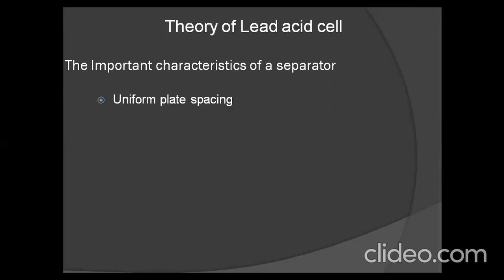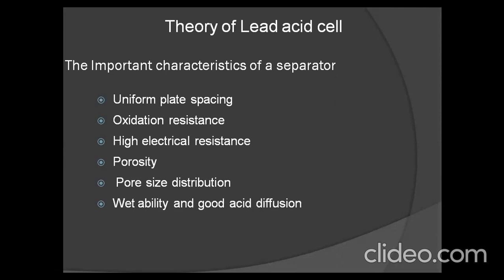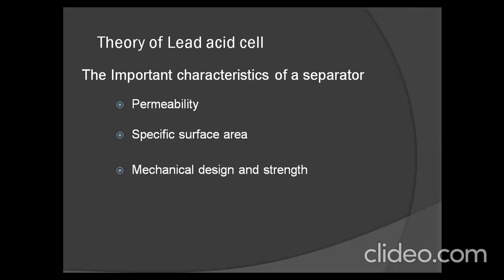The important characteristics of separators are uniform plate spacing, oxidation resistance, high electrical resistance, porosity, pore size distribution, wettability, and good acid diffusion. Permeability, specific surface area, mechanical design and strength, ionic conductivity, and chemical compatibility are also important characteristics of separators.